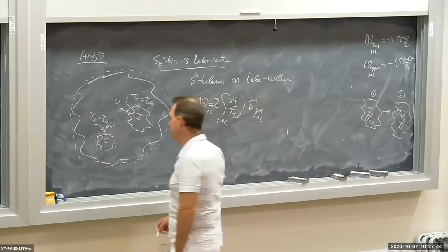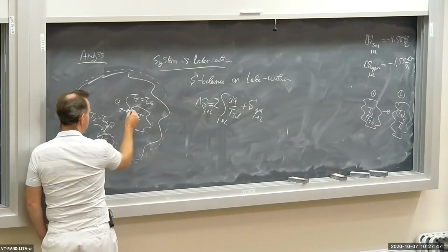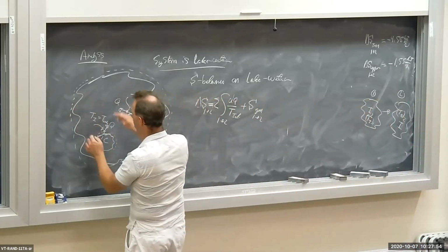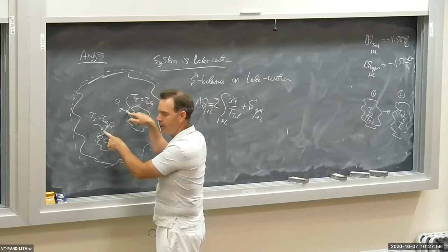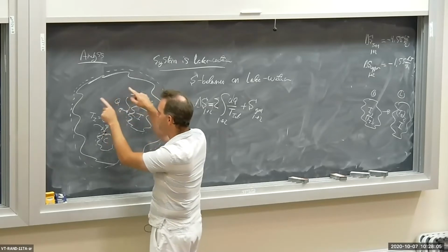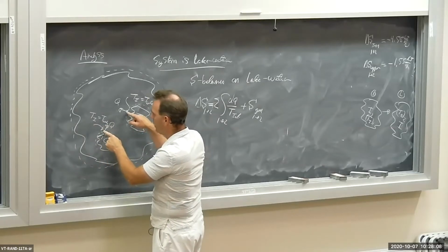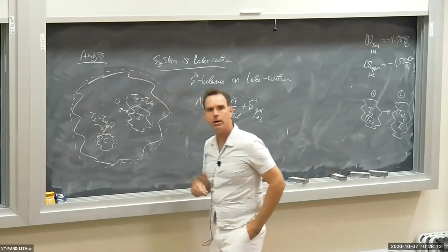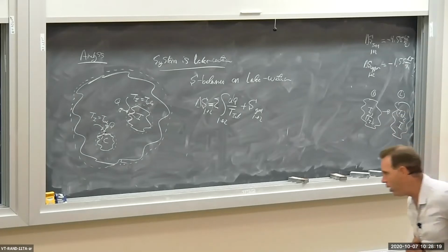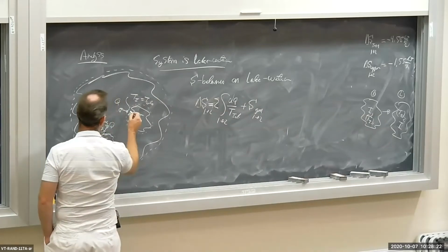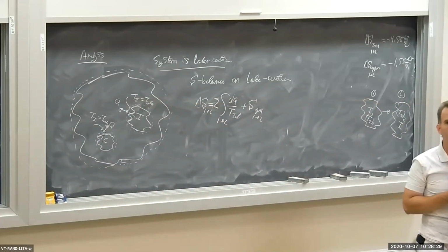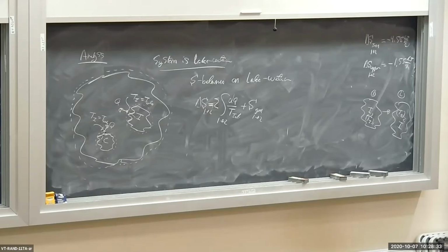Now, what that also means is, because the temperature here is a lake temperature and the temperature here is a lake temperature, where the heat is transferred, as the heat flows into the lake water at the lake temperature, the heat is always flowing at the lake temperature. That means that it's reversible as far as the lake is concerned. If there's no temperature change as the heat disperses throughout the lake, which is large, it's a reservoir, so temperature is constant and is equal to the lake temperature. So if I draw the control volume the way it is, where the interaction temperatures are the lake temperatures, then as the heat flows out and distributes itself throughout the lake water, it will do it reversibly, because there's no temperature change as the heat moves around.